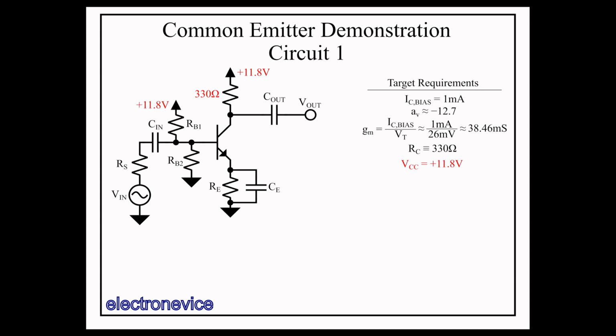So I can put a significant amount of voltage across the emitter resistor. Recall that the more voltage dropped across the emitter resistor, the more reliably I can set the biasing current. So let's put 5 volts across it. This means to get a collector current of 1 milliamp, the emitter resistance needs to be set to 5K. Nearest standard value I have is 4.7K, so let's set the emitter voltage to 4.7 volts instead. So with VE set to 4.7 volts, VB needs to be set to 5.4 volts.